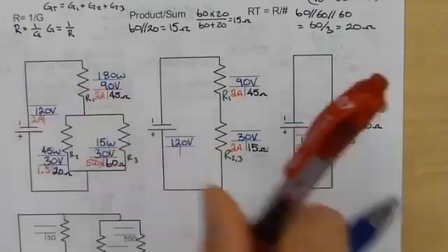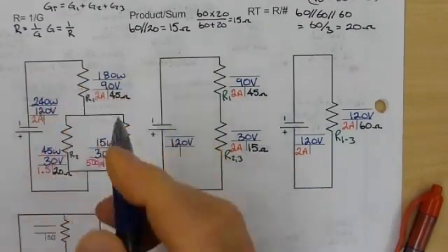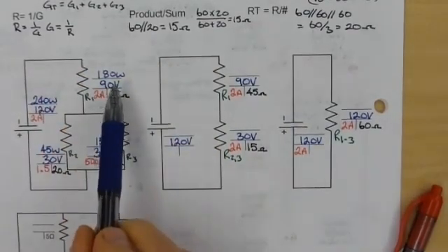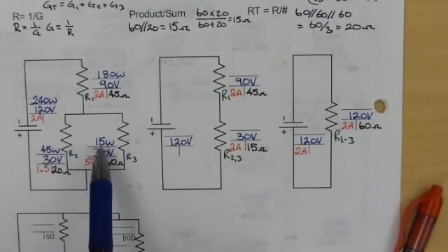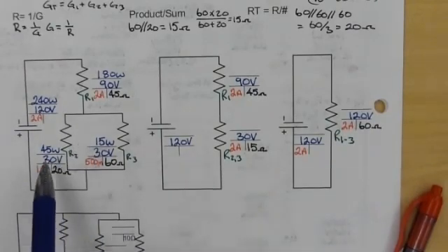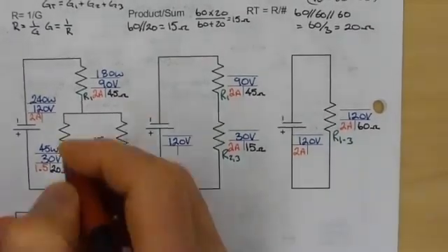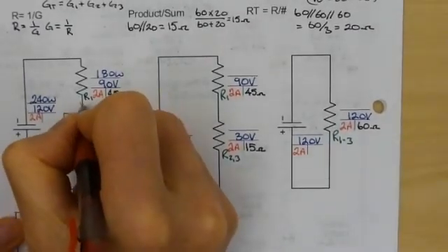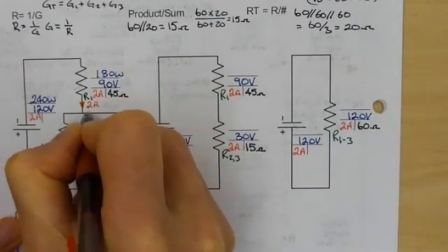Up here, we could add up all of the combination circuit, all the wattages have to add up. So 180 plus 45 plus 15, is that 240? Yeah. Good. So I got wattages right. I've got two voltages, 30 here. And so we can look at another one of Kirchhoff's laws, a node law. So I have 2 amps coming in.